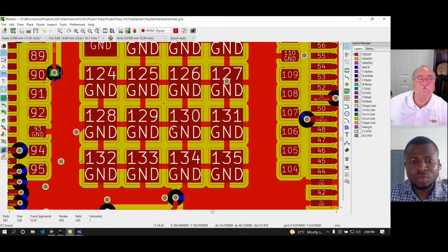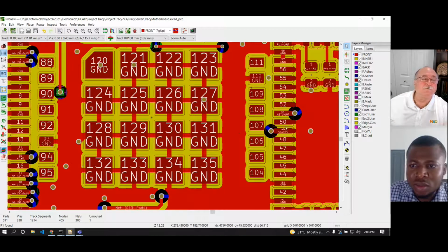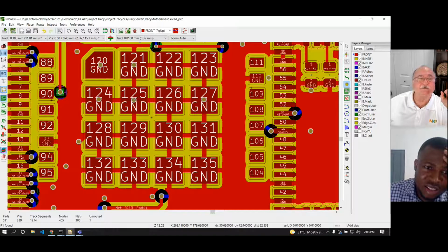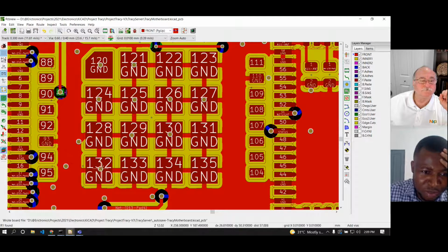If you're doing 500 milliamps, you don't need a waterfall. But if you're doing 5 amps, you're going to need a waterfall. This particular power ground gives you that structure that you need. This particular board may be drawing about 6 amps. Because of the Raspberry Pi, they recommend a 2 amp, but I made it a 3 amp power supply. And the GSM can spike sometimes to about 2 amps. So I provided a total of about 6 amps for the whole system.